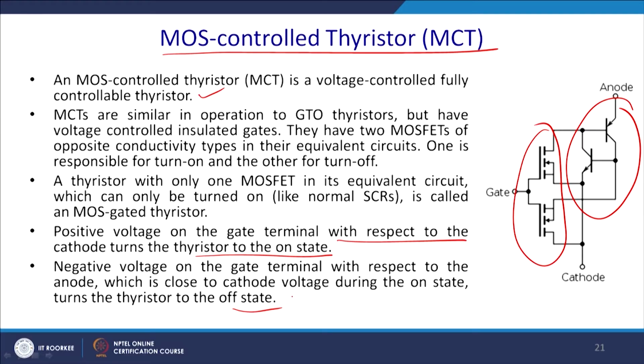So, you will operate at a gate voltage. Since it is an insulated gate, a very low amount of current will flow. Thus, power dissipation, which was a big concern in GTOs, has been considerably reduced, but the problem lies in that its power handling capability is quite low.